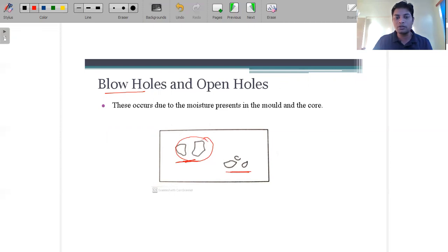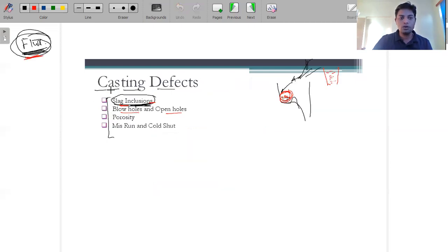So this is the open holes, okay. Now if you will see, okay, this is the blowholes and the open holes. Now, from the day we started discussing this, when we fill the molten material, there is a possibility of gas entrapment, and because of that we are designing all the things. But still there is a possibility, and for that only we are using the gas vents.